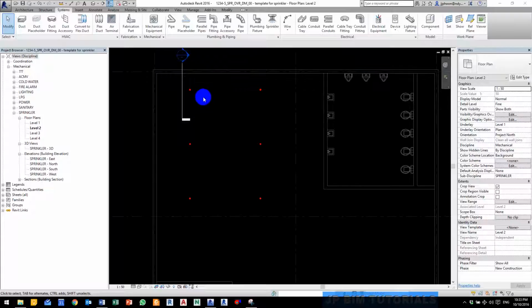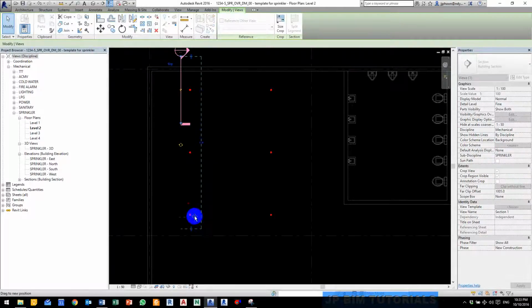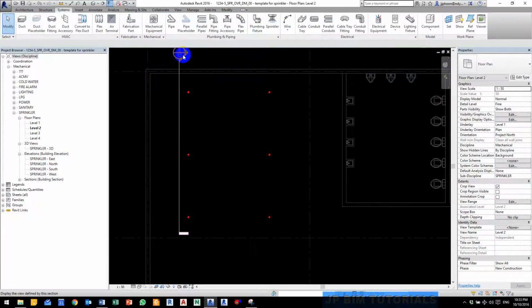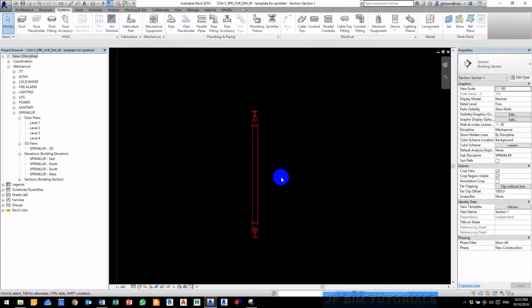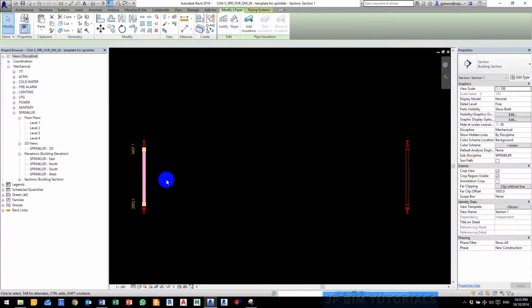So next, what I want to do is draw the branch pipe connecting these 3 points. So I'm just going to extend this section out, click on a hit to enter the section view, and I'm going to model the branch pipe now.